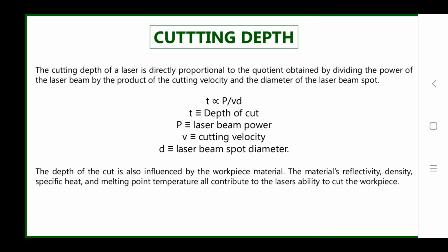The depth of the cut is also influenced by the work material. The material's reflectivity, density, specific heat, and melting point temperature all contribute to the laser's ability to cut the workpiece.